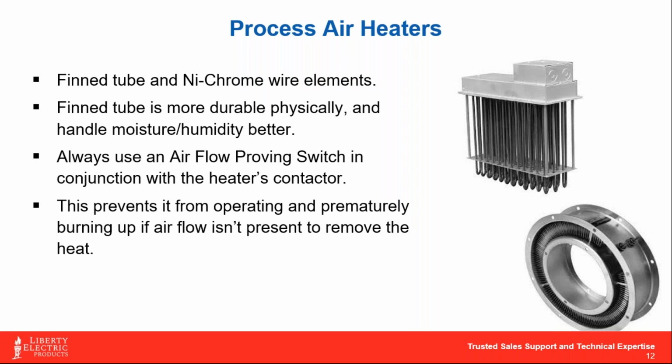And to give you a quick difference between the two, a fin tube element is something like you might see in a baseboard heater, okay? You'll have a tubular element with a bunch of aluminum fins or copper fins, or whatever that material is, steel. If it's got to be anti-corrosive, it's stainless steel. What it does is help the transference of heat. As that element is warming up, it's transferring heat to those fins, which also takes up more surface area within that heater and passes more air through it. These are usually very robust. They handle moisture a lot better than the open coil version does.